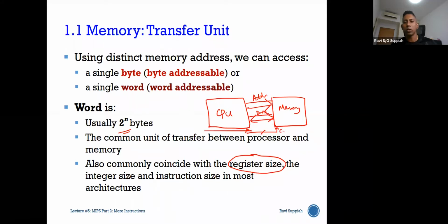Okay, these are basically your control signals to synchronize and do the necessary handshaking. Now, in terms of address bus, just now we saw the size of the address bus depends on how much memory space you have in your system. The size of the data bus is in many cases tied to the size of the internal registers of the processor. Take for example, in our case MIPS, I have a 32-bit processor. That means all my internal registers can store 32 bits of data.